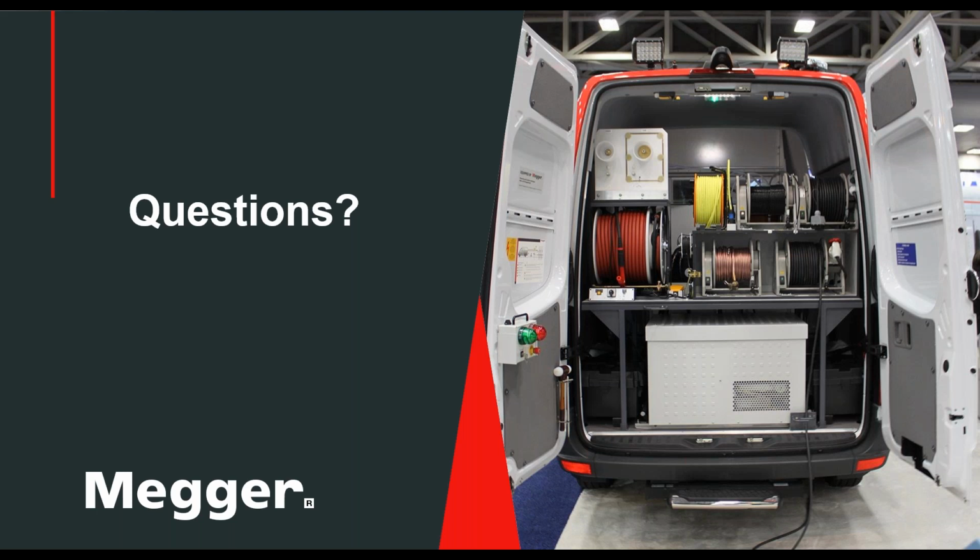And the other thing is, typically on paper cable, most paper cables are used at 13.8 or 15 kV. So if you have a system, the system should have at least a 30 kV high pot capability, so you get initial flashover, and it should have, like Marshall said, enough joules to sustain the arc, so you can get a good thump. Okay.